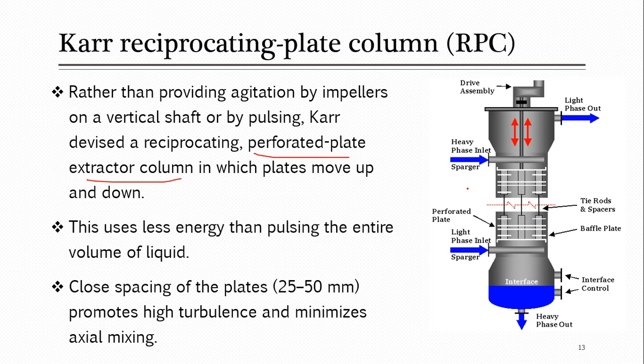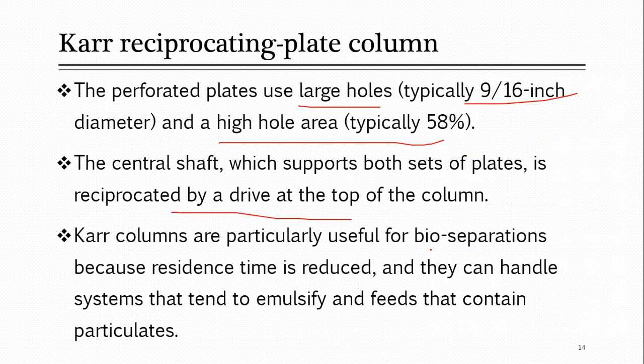When a distillation column is not efficient, you need better separation, and that's difficult. So what you have to do is increase the size of the column. But if it can maintain that purity, or give you a specific purity in a small assembly, that's beneficial. With the help of that, residence time is decreased. In bioseparations, if you give less residence time, that's good for you. So residence time is decreased, and these columns are widely used in the bioseparation industries.